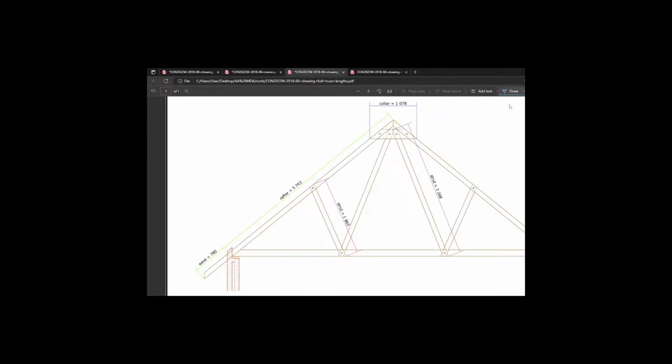Over to a collar, which is something new. And the same applies with the scaling. Just done long strut, done the short strut. Here's your collar. Now, the collar is not so obviously indicated because of the dotted lines and solid lines. So, what you do, I assume either it'll be indicated there or in your spec that there's a collar. And you should know that when they say there's a collar, there's something holding struts to the apex of the truss. So, struts all come together with the rafter and meet at the collar.